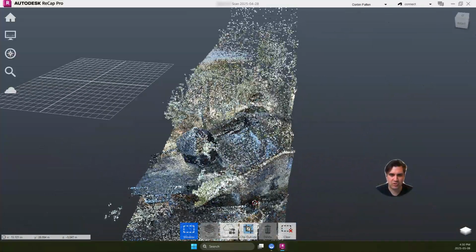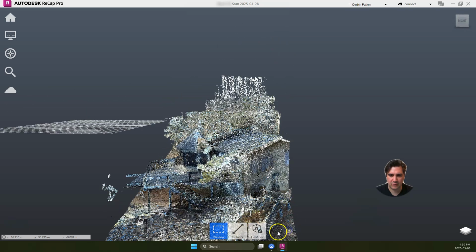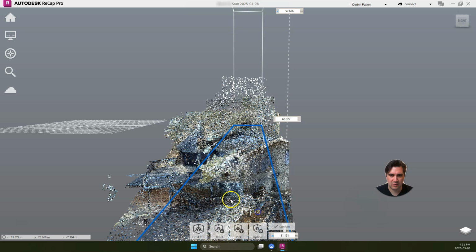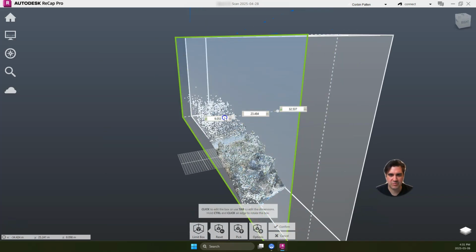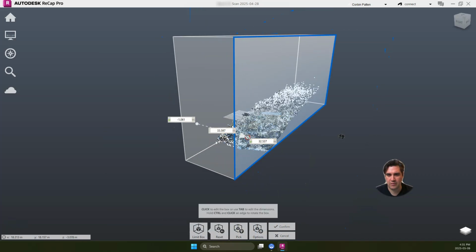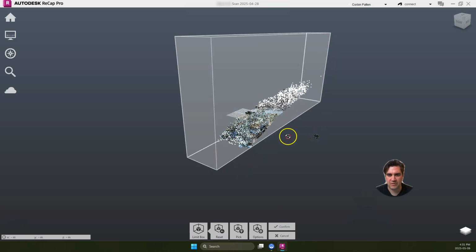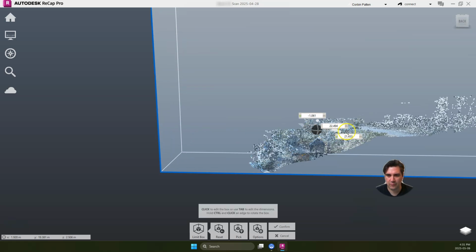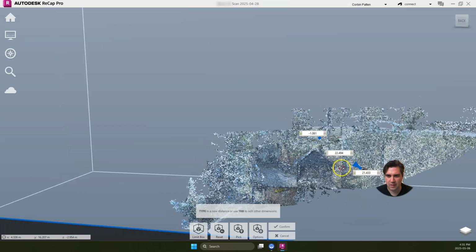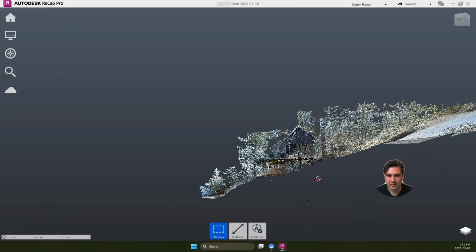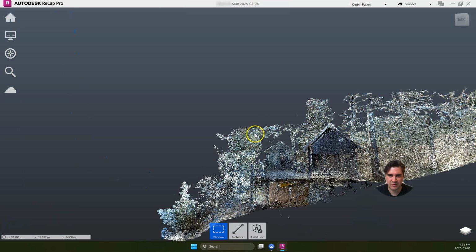And then once you want to adjust that box, we can click clear here. We can go to limit box, we can click edit. And we just might drag this part over this way, and maybe drag this part over this way. And so you can just keep going through this model like this and classifying all those different scan pieces.